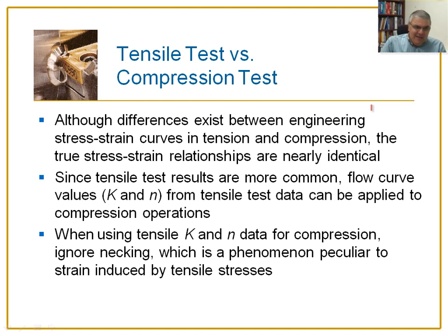Since tensile test results are more common, we use the tensile test results. However, we always check to make sure the material will not buckle before it reaches its ultimate load carrying capacity.